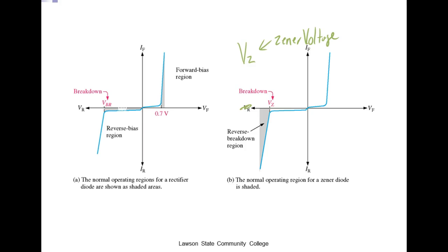And we're going to operate this thing reverse biased. By the way, you check it with an ohm meter just like you do a regular diode. You put it on the diode scale. One direction is going to measure about 0.7 of a volt if it's silicon. Flip it around and it should measure open, because your meter's not going to put out enough to exceed the breakover voltage. No, that's not true. I've seen some Zeners that would break over at about 1 volt in data sheets, but I've never seen them used.